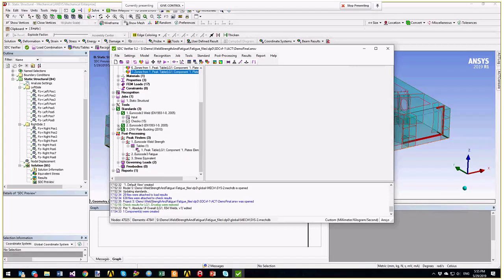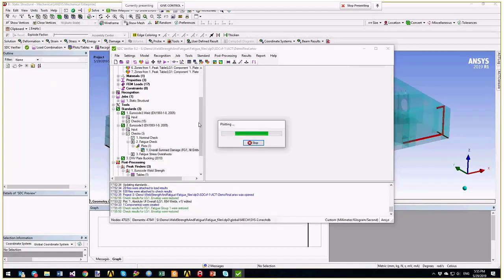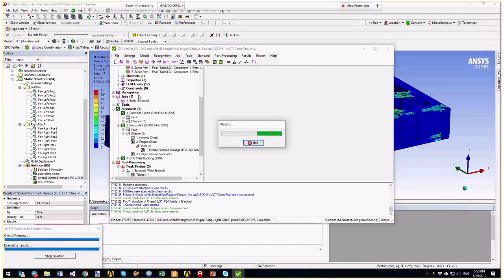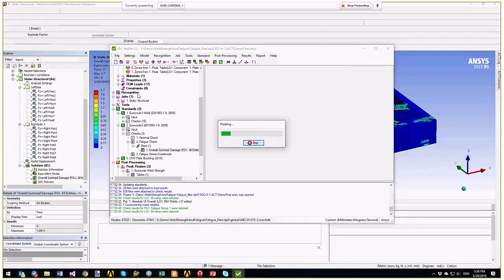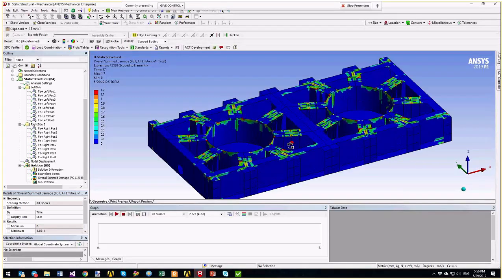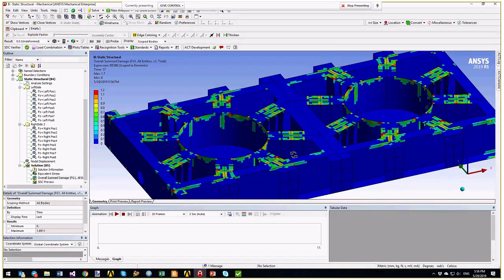We have the same with Eurocode 3 fatigue. We make a plot for fatigue damage, and we display that for the fatigue group, because the rest of the checks we do for the load group, our envelope, which gives you the highest results. For the fatigue group you need an additional stress history, so you need to do a calculation for the fatigue group, and you can see that we have some problems with fatigue in some spots.